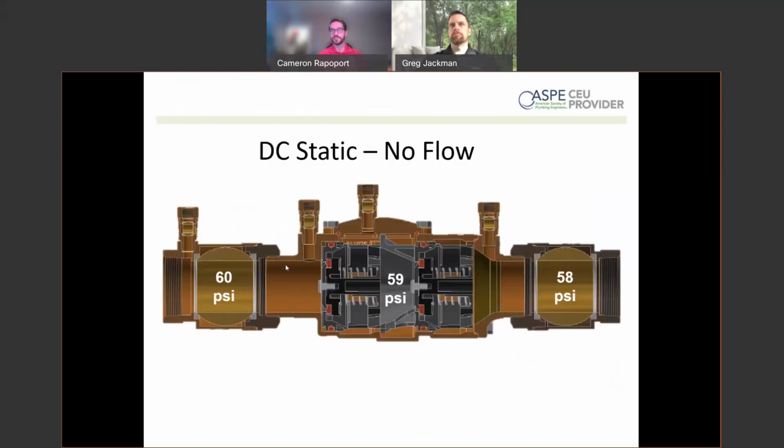Right, these are pretty simple. There are 2 checks, 4 test cocks, 2 shutoff valves. The shutoff valves are important for isolation for testing, and the test cocks are used to test it. The individual checks have a minimum of 1 psi pressure loss across them. So as soon as the differential across that check goes to 1 psi, it should be shut and drip tight. And that is what they are testing for when they go and test these valves.